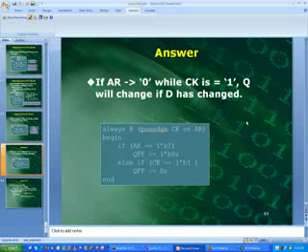We covered a bit of material today. You're probably going to want to go back through this, and also start looking at these, for example, the one-wire transmit and receive, so you can see how the state machine stuff was done in there. You can see how the combinational logic was done versus how the flip-flop logic was done. Look at those two always blocks in there, and that'll give you a good example of how to write RTL code.